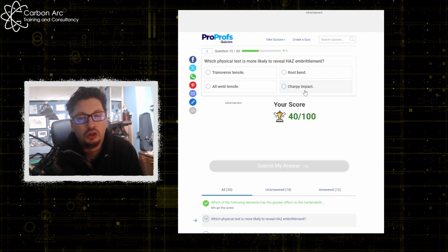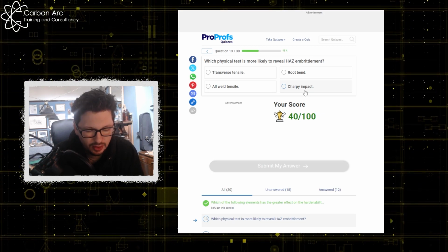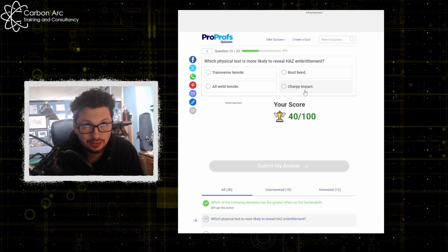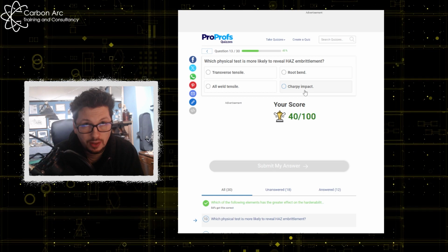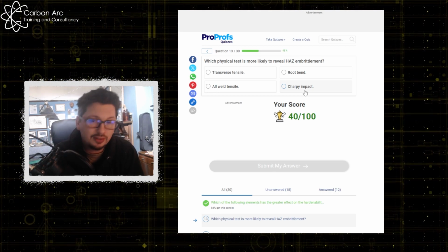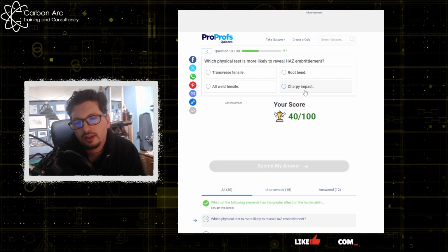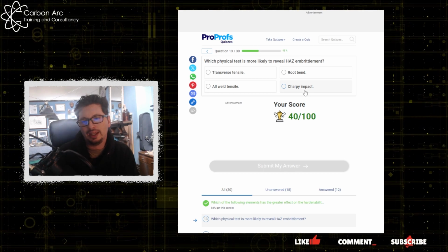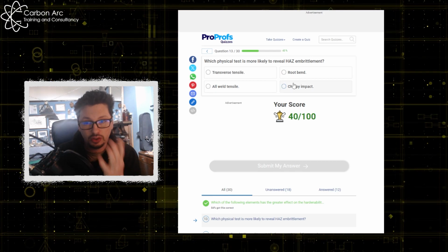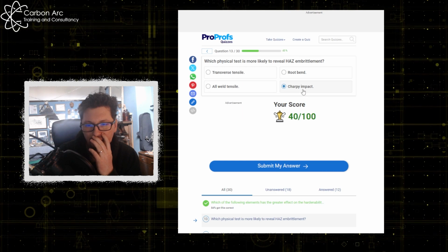because you would have a lower impact energy. What that is showing, in my mind, is a lower amount of toughness, which I guess you can pull into the brittle side of the transition curve. I think the best one there, even though I would argue the bend would show it to some degree, more likely I would go Charpy impact.